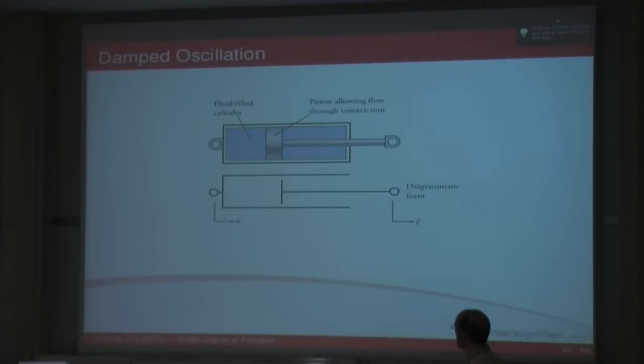A viscous damper is essentially a piston in a closed cylinder, and there'll be some fluid in that cylinder. In the piston, which is not shown in the diagram, you can imagine there are some small orifices, little pipes, constrictions, and so as you push the piston, the fluid is going to go through those orifices to the other side. Very straightforward to understand. But because of those constrictions, the speed with which the fluid can go through is limited, and so you've got a force in the opposite direction from the way you're pushing, and that force is dependent upon the velocity you're trying to move it.